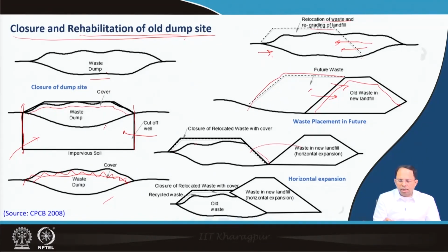Some amount of waste could be relocated over here, and we can have a fully new landfill design at the side of the existing landfill. Sometimes it could also be designed in this way, where it partially rests on the existing landfill and partially sits on the side of this particular landfill. So this is how an existing landfill could also be redesigned and re-engineered to take care of new waste in a more protected facility.